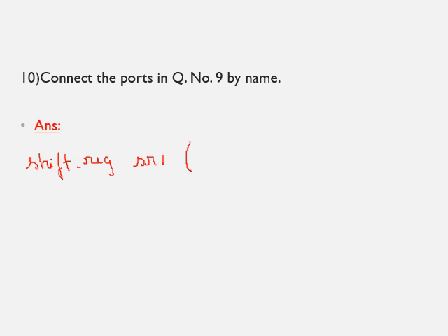Now inside the braces, in the actual module definition, the output port is register out, that is to be connected to the register out. This is in capital, this is in the top module, that is the stimulus module. We have declared the corresponding signal as register out in capital letters. Okay, so now here since it is connect by name, the order is not important.